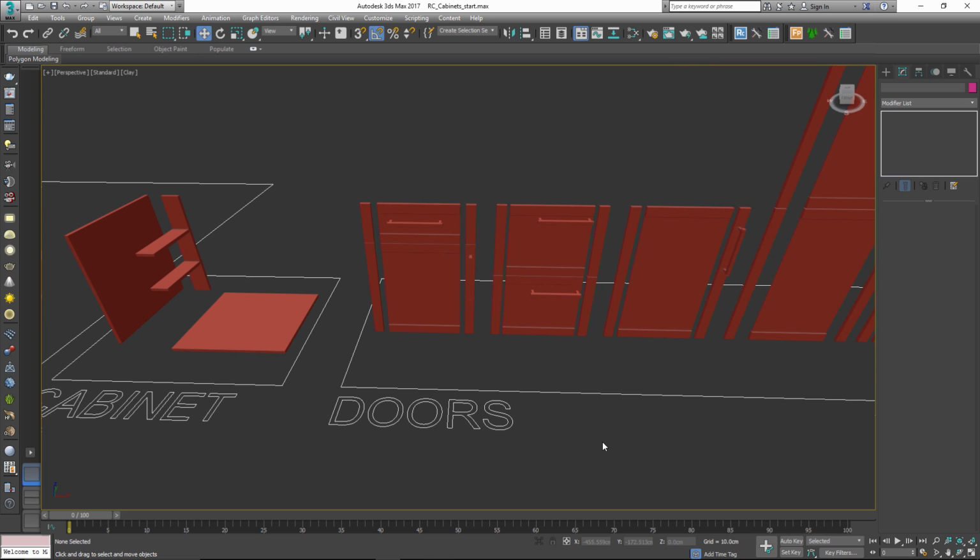The various elements have to be prepared in a particular way, but it's no more complicated than slicing your pre-modeled doors and other parts into sections so they can be easily scaled to different sizes. Normally, for example, to build a kitchen you'd need all your different doors and carcasses in different widths, but using this style you need just one for each type of door or drawer combination.